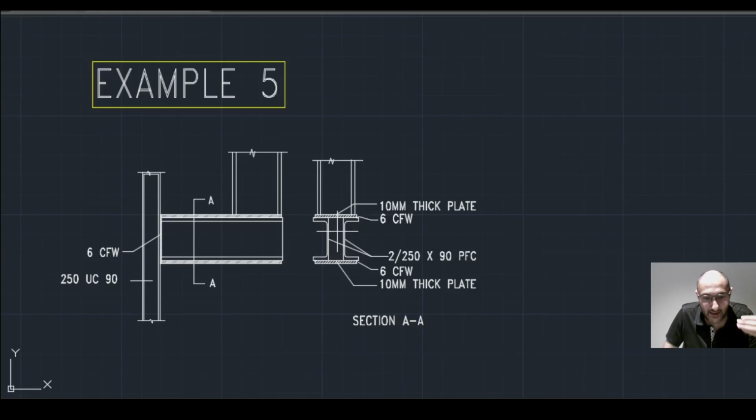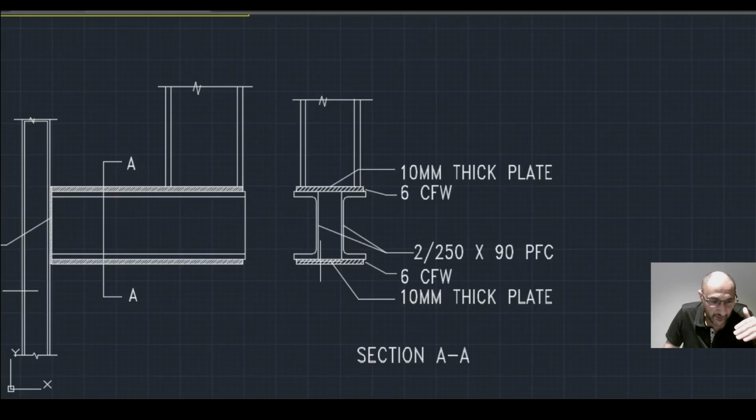Now, since the steel plates and the beams all have one modulus of elasticity, we took the entire elements as a unified section, provided that we check the shear stress in the welds where there is a top and the bottom plates in these planes up here and down here, and the plates where the beams and the plates are in contact. So the plates here connect the two beams together, unifying it into one element.